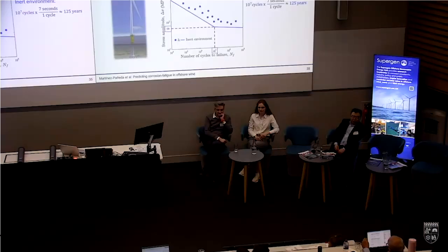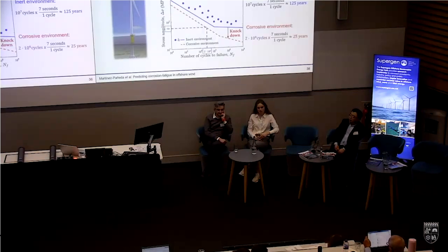And of course you may wonder here, okay, we know that corrosion accelerates this fatigue damage process, so how do we account for corrosion in these things? Well, we do that by taking into account a knockdown factor, which is not only very empirical, but also has some obscure origin. But then once you do that, you do the same process again, and you get 25 years out of that.